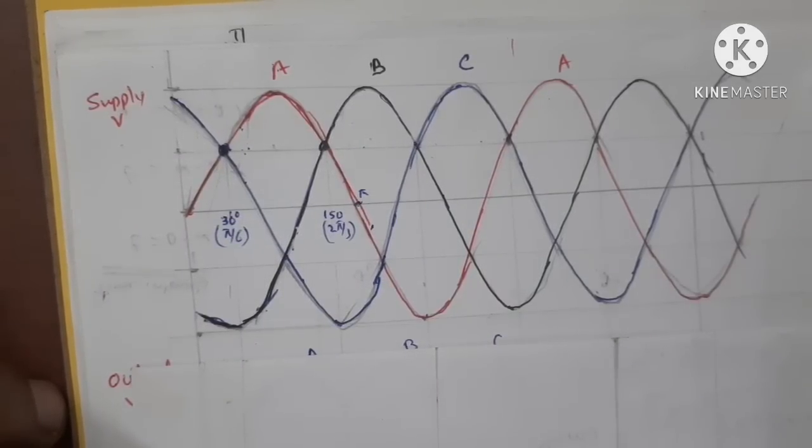But in the R load, what we have seen is that when omega t is equal to pi, that corresponding thyristor cannot conduct, and the next thyristor will turn on only after alpha from its measuring point. So all those things we have seen in the previous class.